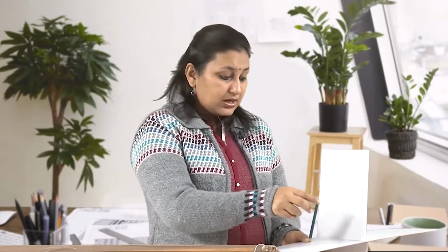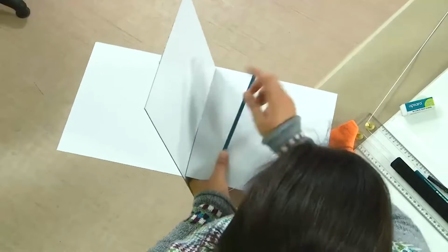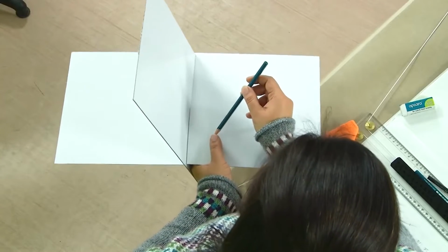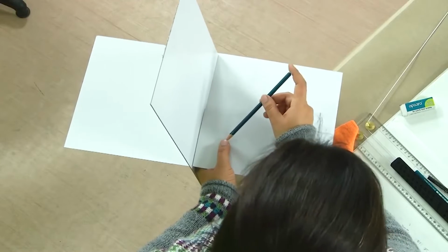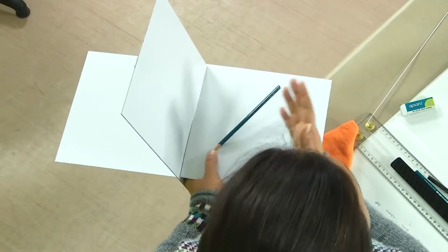So, as it moves like this, the horizontal line, the locus of this point which is on top, remains the same as the lower one remains pivoted. In front elevation, we will see that the top point is moving in a straight line. The top point will continue to move in a straight line in such a manner that the line now makes an angle of whatever, say 30 degrees, from VP.